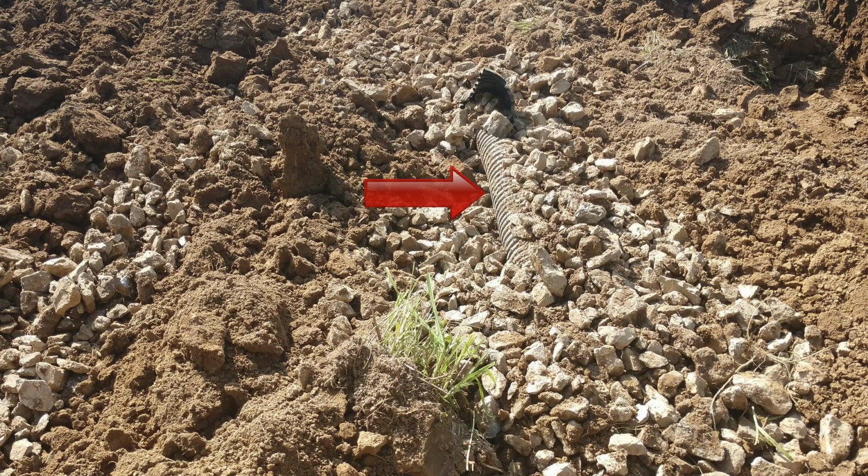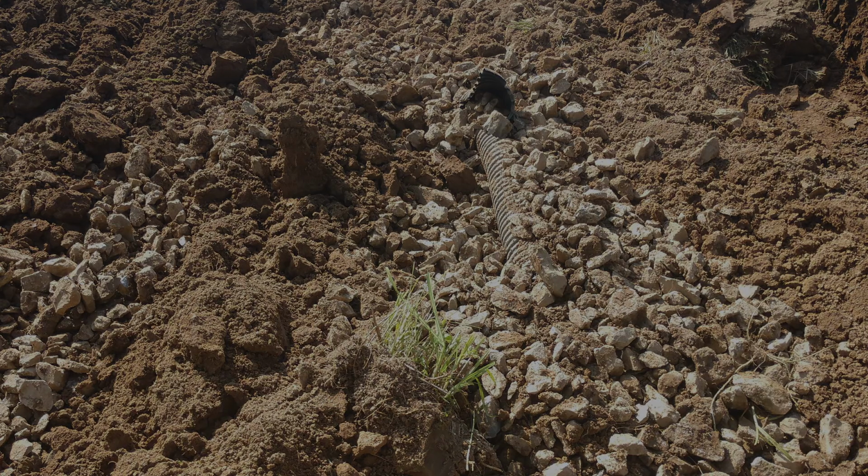This plastic 4-inch diameter drainage structure was surrounded with gravel so it would drain. When restoring a wetland, it's best to remove the entire pipe and all the gravel and then fill the trench with clay that's compacted to restore the wetland.